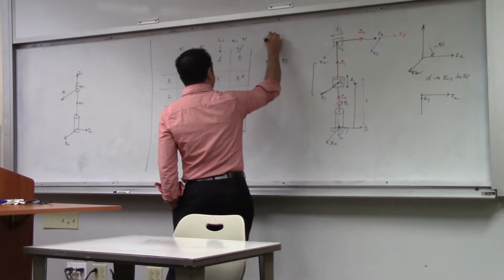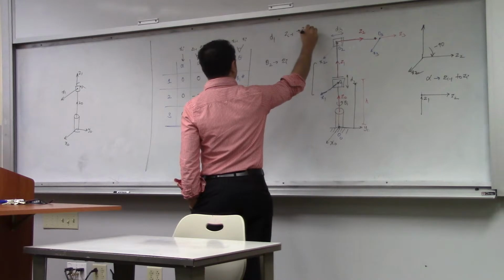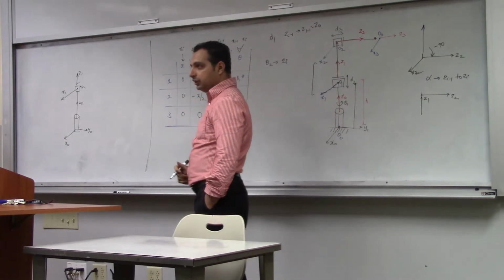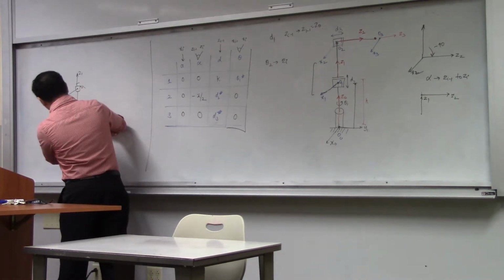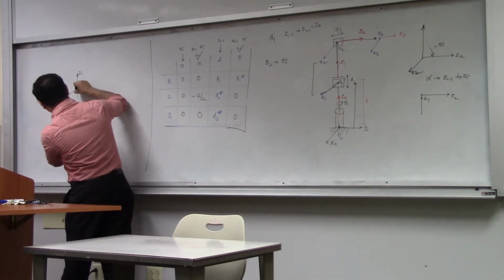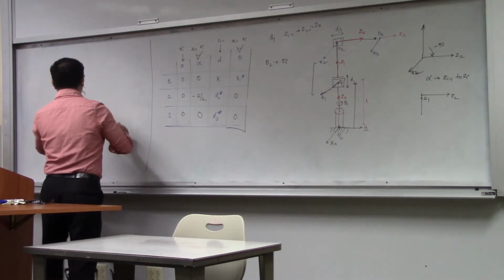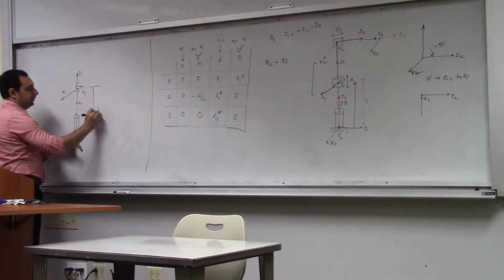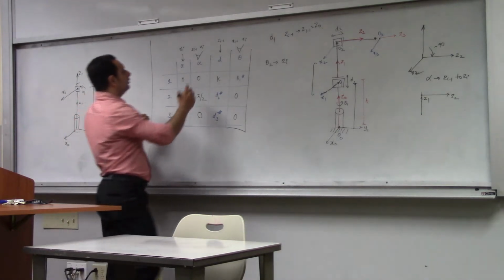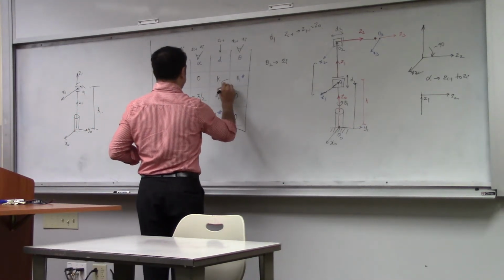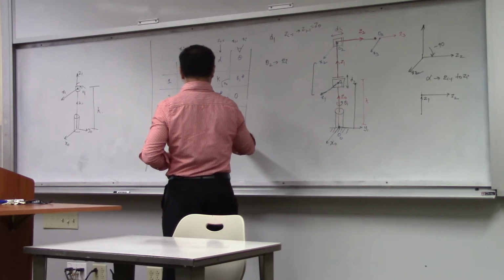So if I want to measure D1, I have to measure along Zi minus 1, so that is measure along Z0, okay? So Z0 starts from O0, right? So you measure from here until it intersects the next one, O1. So this distance here is given as D1, all right? This distance is measured along Z0. This distance is measured along Z1. This distance is measured along Z2.